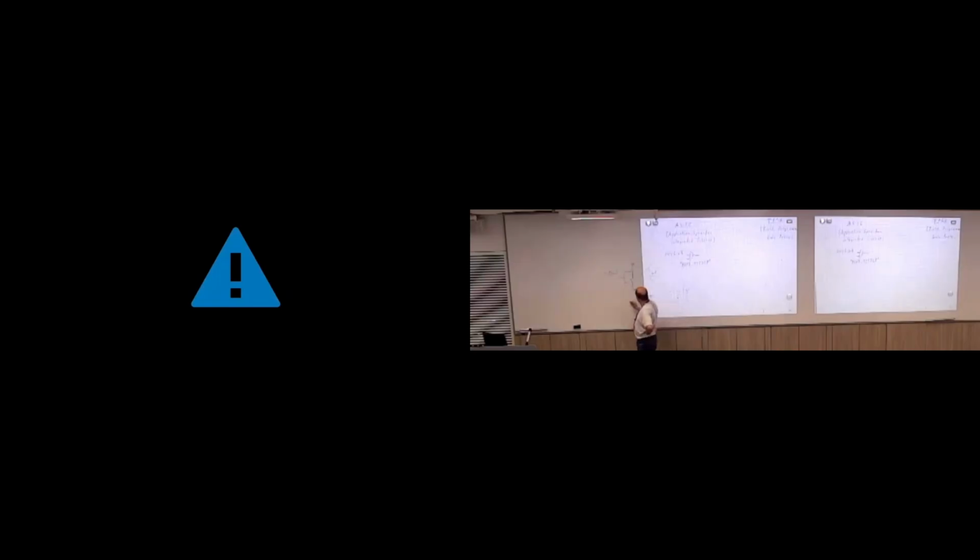So we have this here is x1, this here is x2. We are not yet complete, but if this here is VDD and at least one of the inputs is 0, then the output y is connected to VDD, is 1, right? Good. Then if both are 1, we want to have the output to be 0, right?